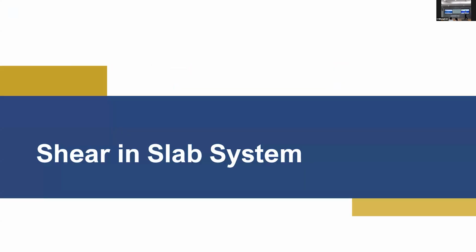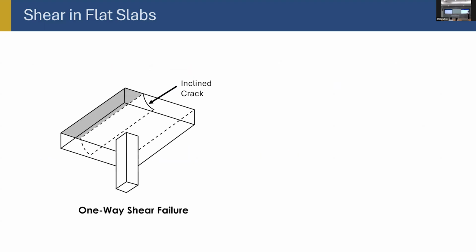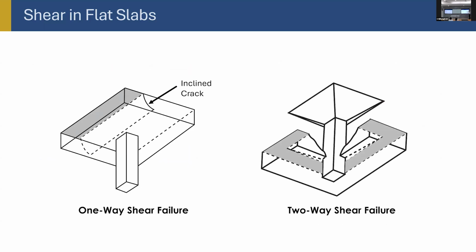Okay, so that's the bending problem in the slab and the two-way action and the post-tensioning and the way that we distribute. One more important thing that we need to also consider is the shear in slabs, in flat slab, and that is the punching shear. So this is the one-way shear, and this is the punching shear. What we are most worried about is the punching shear in flat slab, because the slab can break around the column and fall down. And this is the most common failure type in slab systems that has occurred so many times.